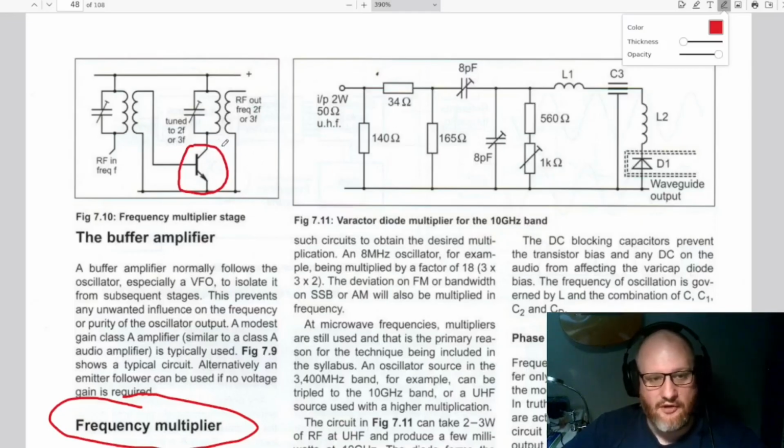And when we have distortion, that creates what we call nonlinearities or harmonics, and then this tuned circuit on the collector is being used to select the desired harmonic. So we may have an oscillator that works for the 40 meter band. We drive this transistor into distortion, and we get the third order harmonic would be 3 times 7 gives us 21, which might be just right for working on the 15 meter band.